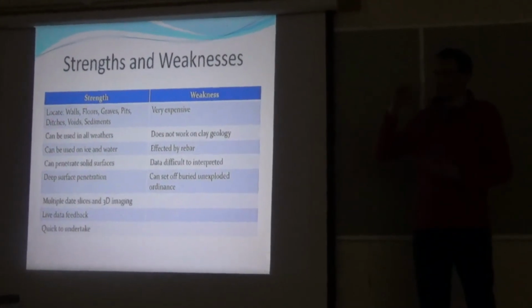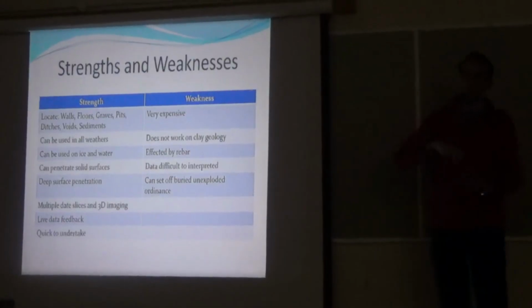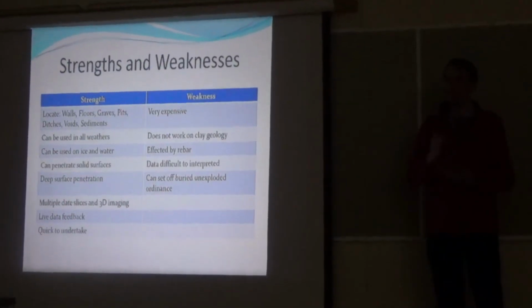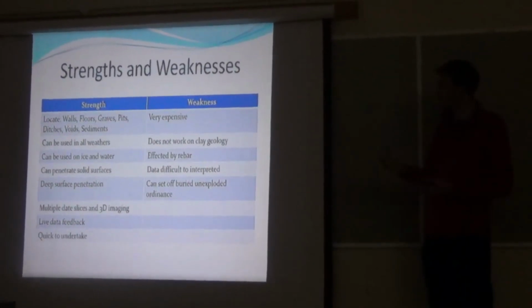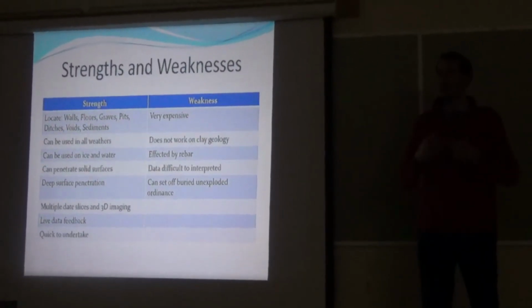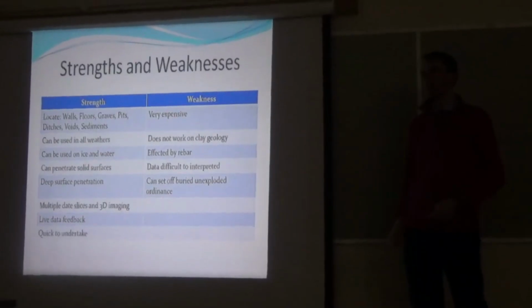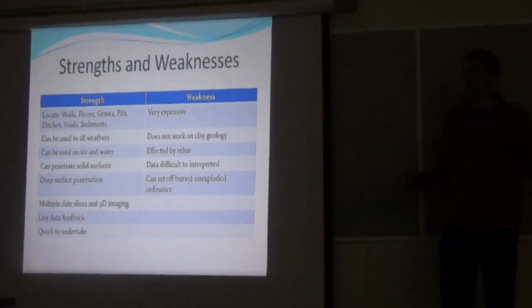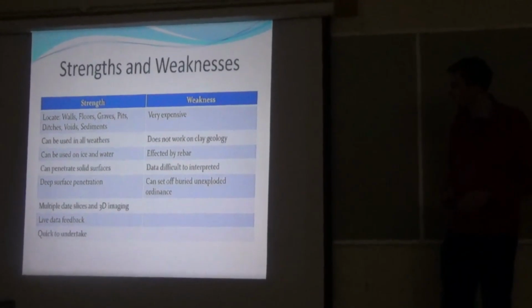So the instrument will send out a signal, but because rebar is so dense and underfloor heating pipe is so dense, it will just reflect all the signal back and you get no penetration into the ground. So you just see that rebar in that concrete.